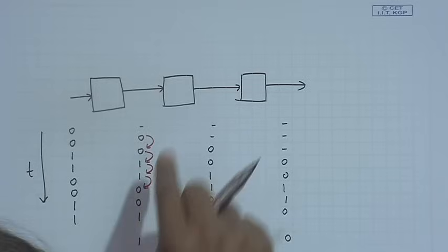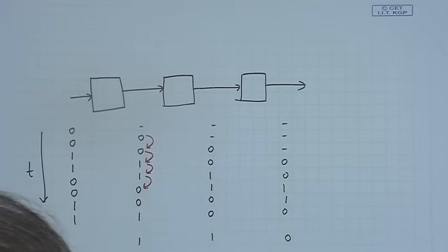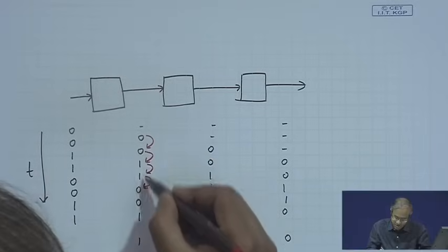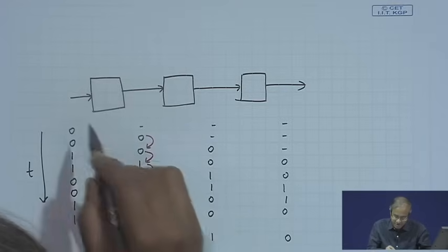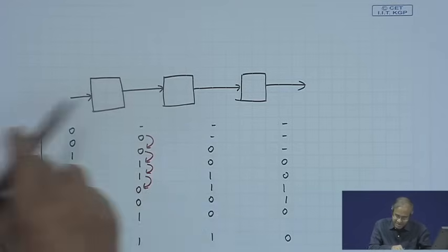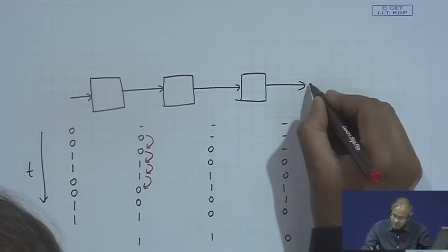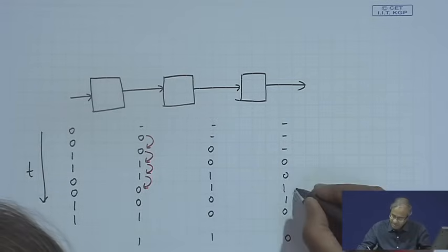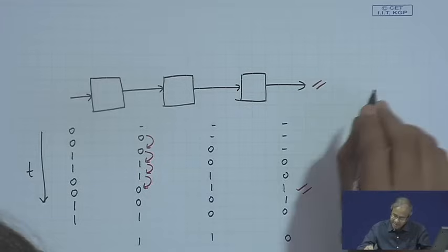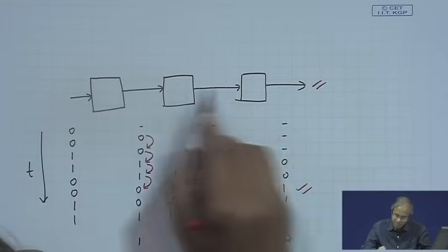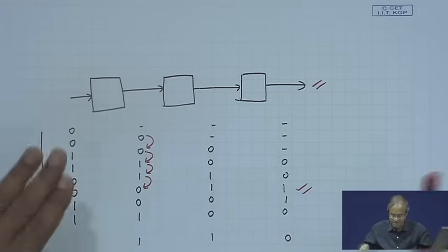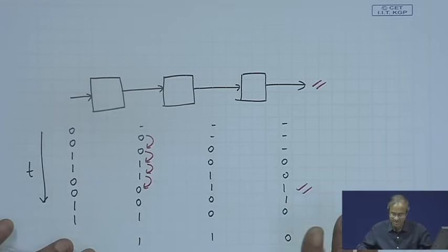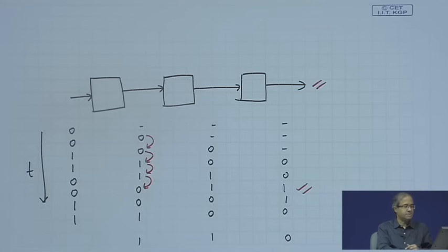That is how we test a flip flop, that it can store each logic value and it can also have all possible transitions. Just by applying this pattern serially, if I observe that the expected pattern is coming out here, I can be sure that all these flip flops and also their interconnections are working correctly. This is how the shift register testing is carried out.